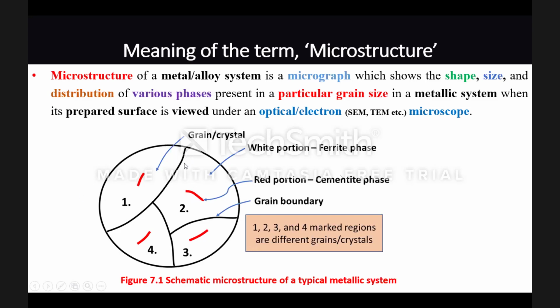And somewhere over here in the black region, these two grains collided because their growth was now obstructed by the adjoining grain. So this region shown in black is not a crystalline region. This is rather an amorphous region, at the boundaries of the grains. So this region is called the grain boundaries. This entire black region is the grain boundary region, which I have labeled over here.